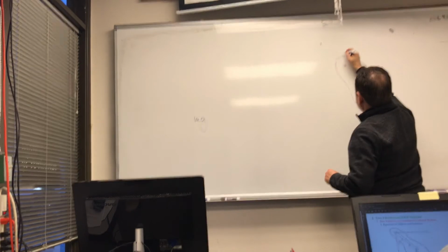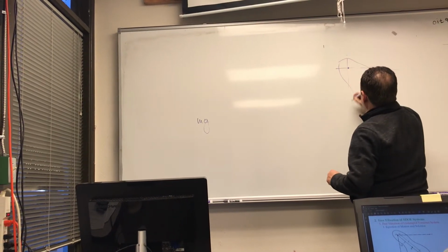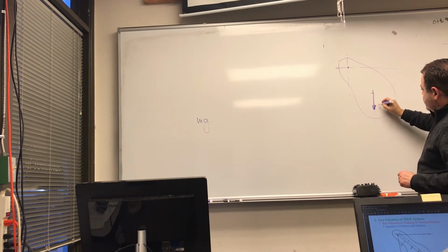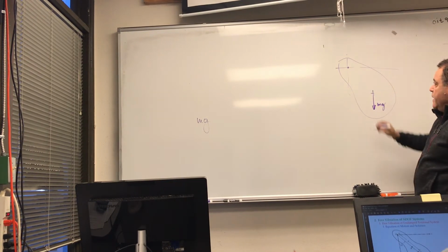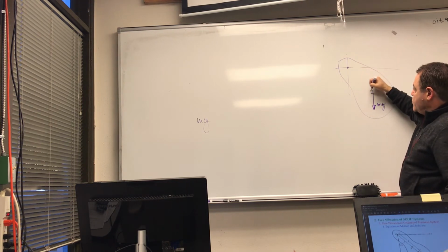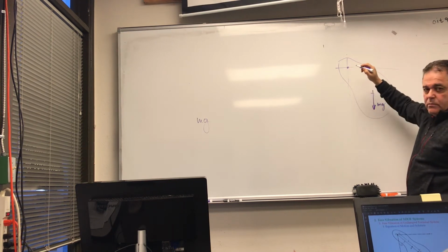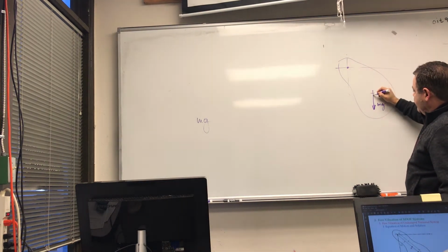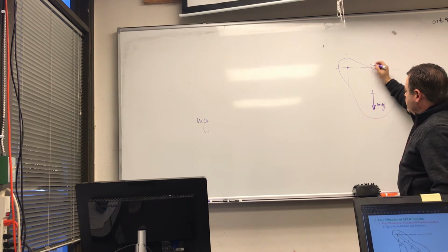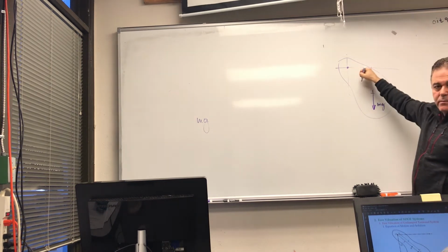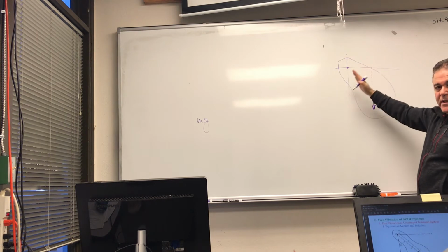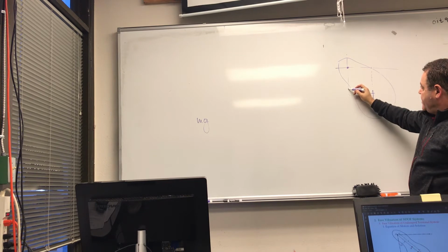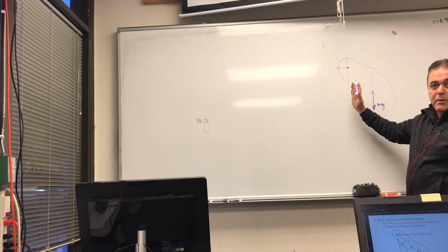Okay, let's say I'm rotating about this point, and let's say my center of gravity is right here, and my weight is right there, mg. I want to find the moment of this force with respect to point O. This moment always has to equal the force times the shortest, perpendicular distance between the two. If my force is here, its moment arm is zero.